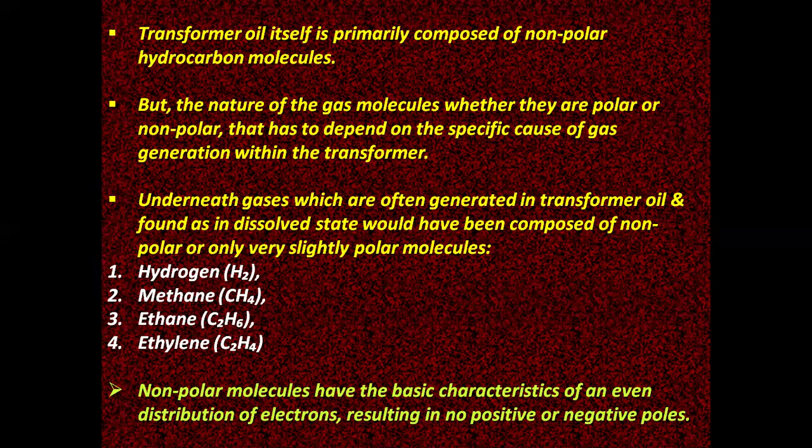The gases often generated in transformer oil and found in a dissolved state are composed of nonpolar or only very slightly polar molecules: hydrogen, methane, ethane, and ethylene.